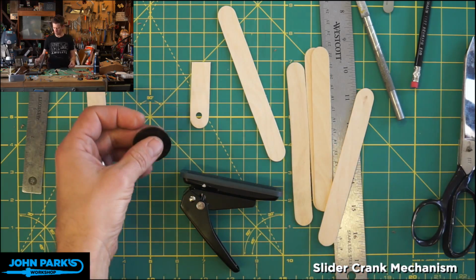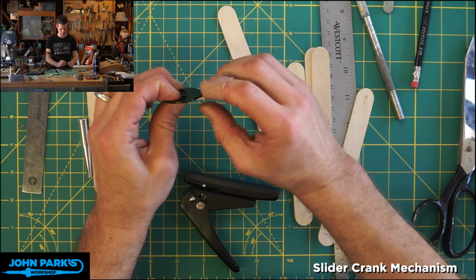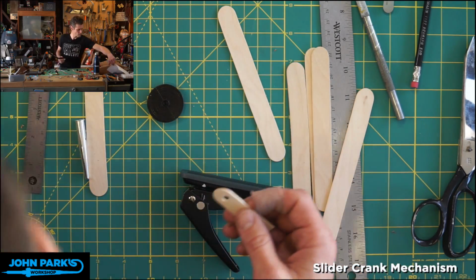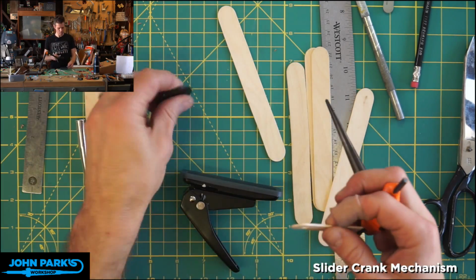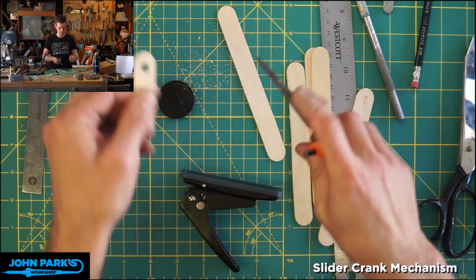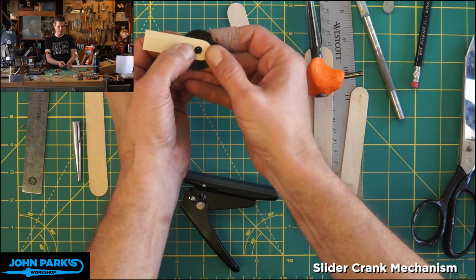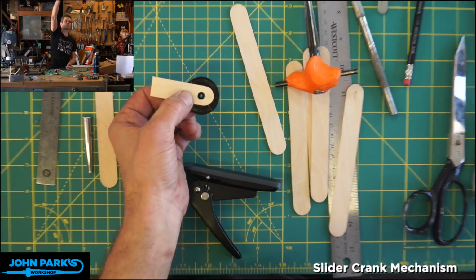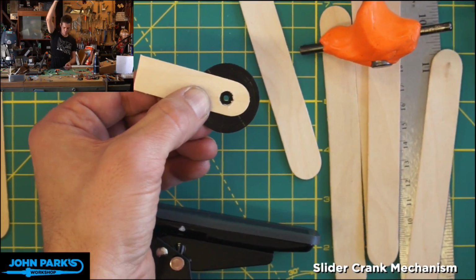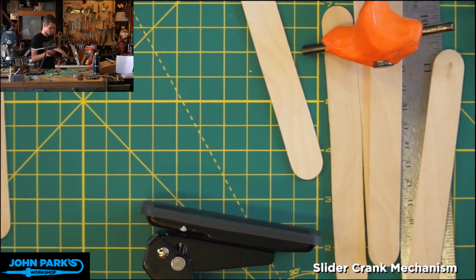You know, let's use this big one. So since we have this hole here, we can fit. Yeah, we can get that on there pretty good. I'm going to bore that out a little bit, I think. Grab a reamer. There's a little lip on this axle of that servo horn. So I'm just going to drill that out. Okay, that'll fit flush on there. And so that little hole is used to, by having that there, we can also screw down into the servo, which isn't always necessary, but it's nice if we want it to be on there securely. So I'm just going to hot glue that on here. If this will reach, yeah.